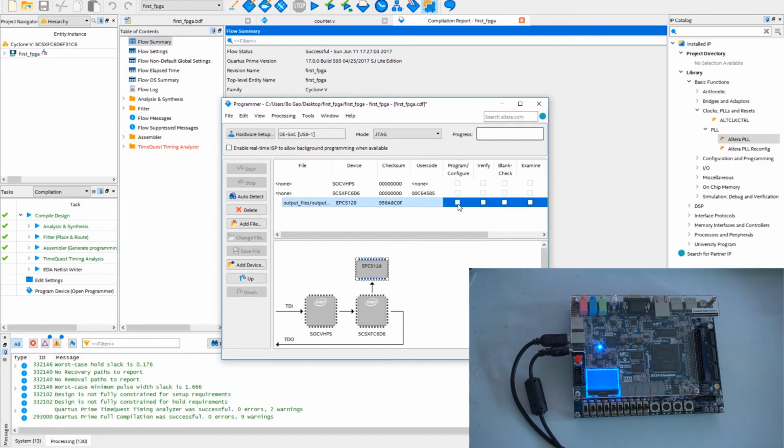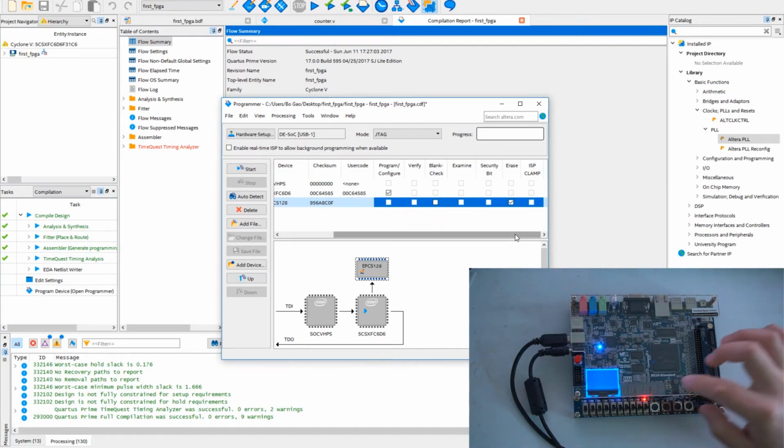You want to, let's say you can erase that EPCS, and then we won't have any of the configuration, or we can just override from program configure. So let's say I want to first remove all the features of the board, so we can verify that. That's actually weird, because it's already running a blinking application. So we first erase that and see what happens with a blank EPCS.